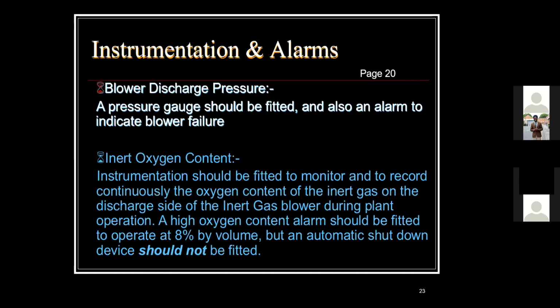Another alarm that you can get, as I said earlier, is the oxygen alarm. This is very common because I believe a lot of us here are tanker men. When the oxygen content is high, you are going to have an audible alarm. And when it gets to a certain level, it can automatically shut down because it doesn't want to supply the inert gas system with high oxygen content into the tank, which can actually lead to explosion.